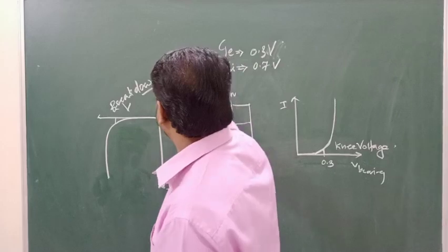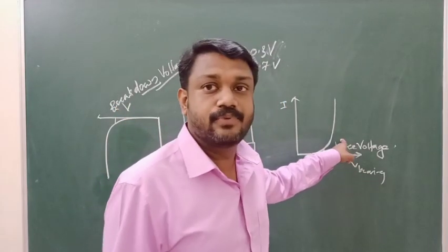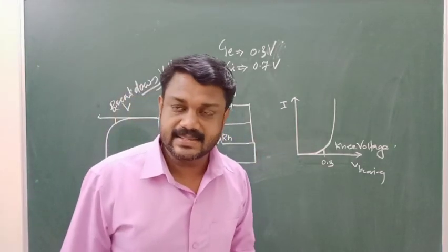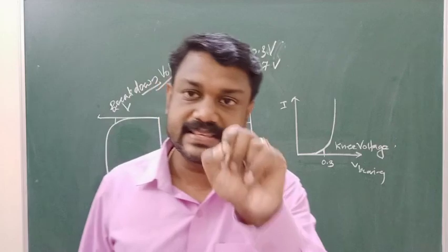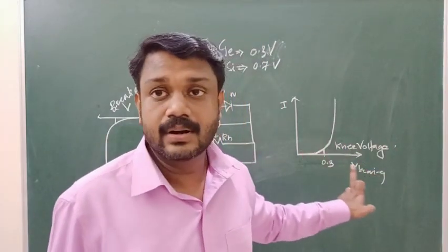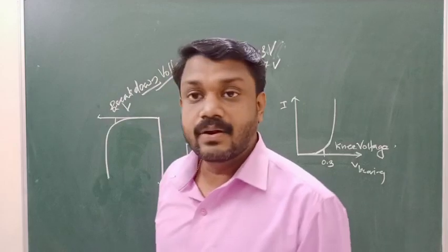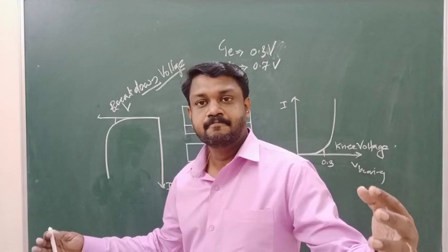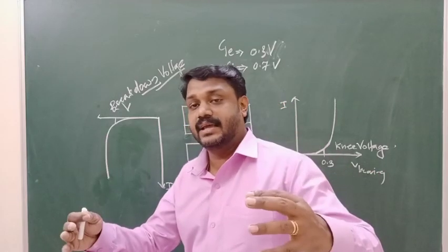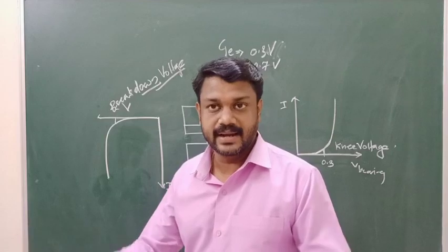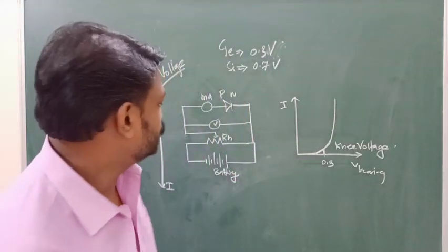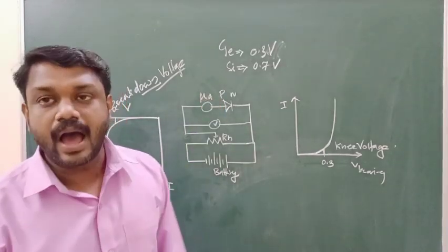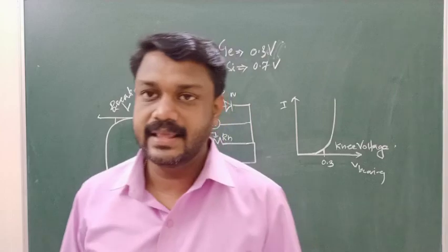So two voltages you have to remember here: knee voltage in forward bias, and breakdown voltage in reverse bias. Knee voltage in forward biasing is the value of biasing potential equal to our barrier potential. Here, breakdown voltage is the biasing potential at which the depletion region breaks and the minority charge carriers, already in the bound state, become free and cross the junction to maintain a current. Anyhow, it is due to the minority charge carriers, so in reverse biasing the current is obtained in the microampere region.